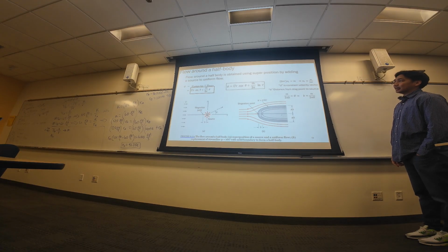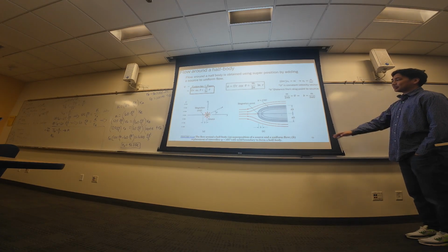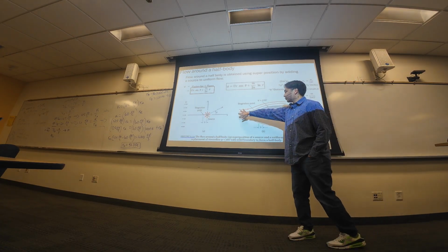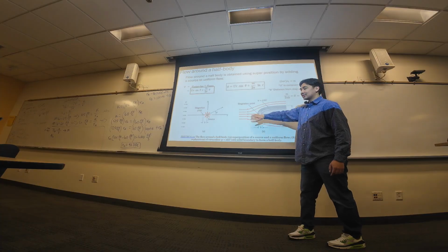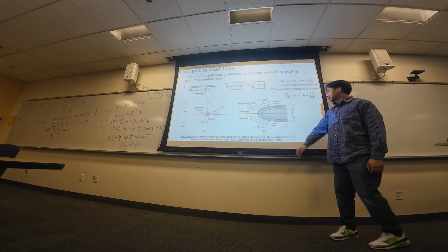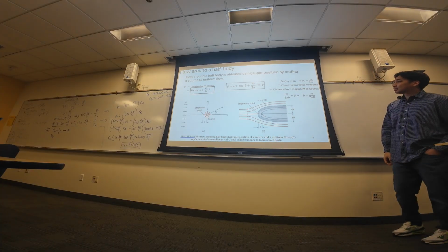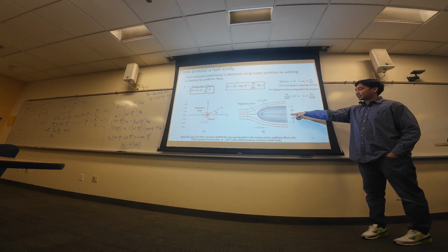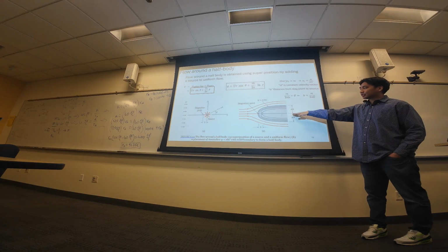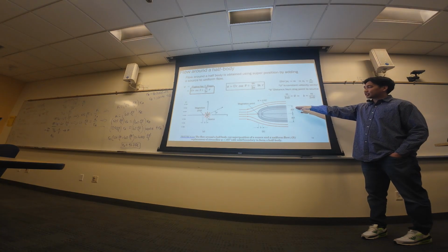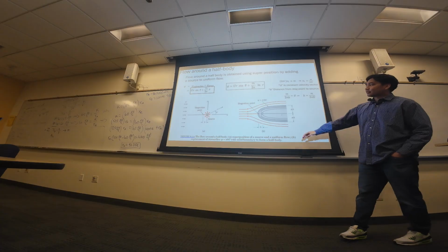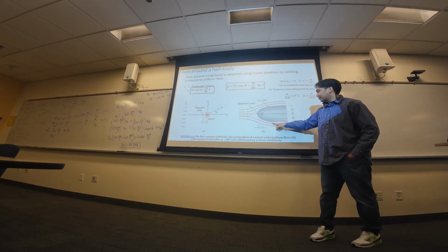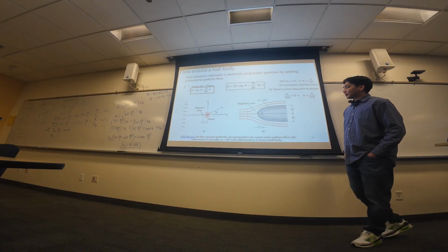Okay, and why is that? Because it's uniform flow plus source. So uniform flow is right here, these red lines. Source is right here. Then you have your pi b, just the distance from the center of your source to the edge of the boundary condition here. And you have psi equal to pi b U on this boundary, the outside layer of this half body.